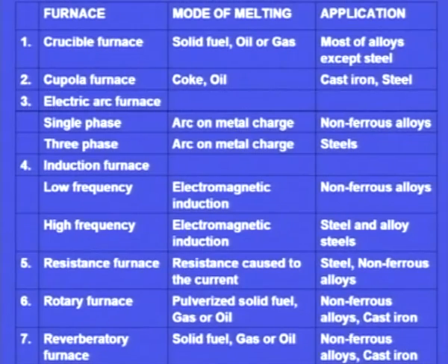Sometimes in cupola the accurate composition control is not possible. We tap the molten metal from the cupola and feed it in the reverberatory furnace. Here we can control the composition, we can add the alloying elements. That is how we can control the composition accurately. So this has got multiple purposes, this reverberatory furnace and rotary furnace.